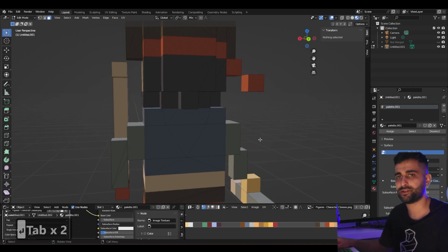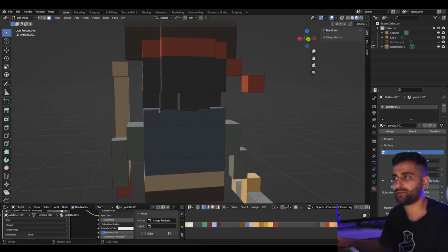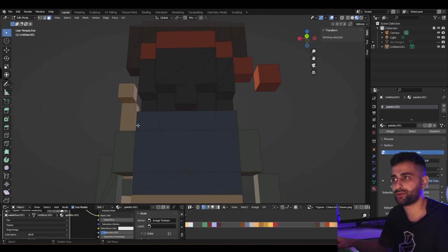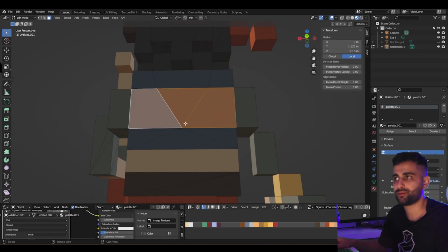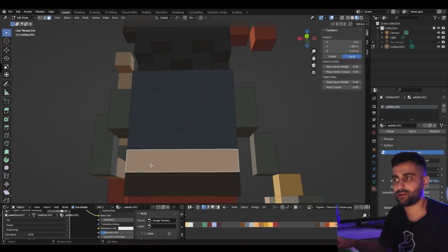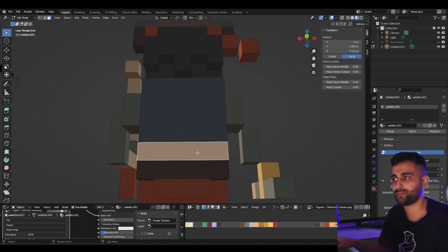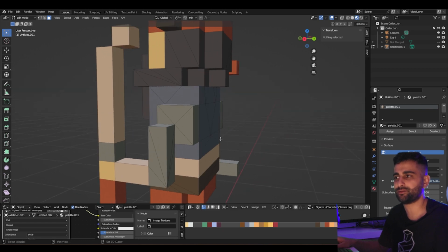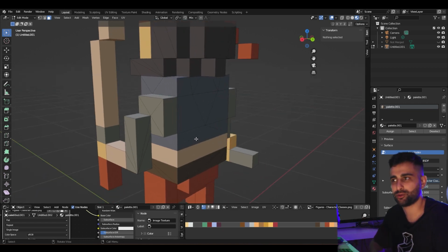So you can see here in this example that I've modified the topology to be as smooth as possible. Here we've got 5 vertices, and I've broken it up into 2 triangles and 3 quads, which then collapsed into a triangle and 2 quads here, and then connected it in such a way that it goes back to the single quad here. Now this isn't too necessary because there's not going to be too much movement in this location, but it's just as a demonstration of how to clean up the topology. It doesn't have to be perfect, really.